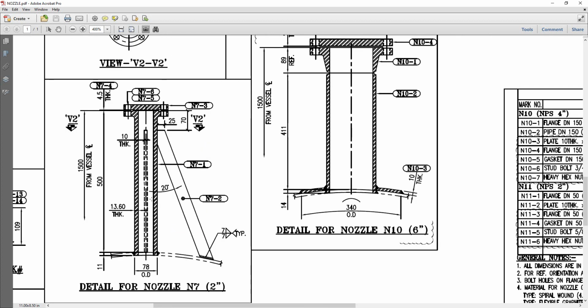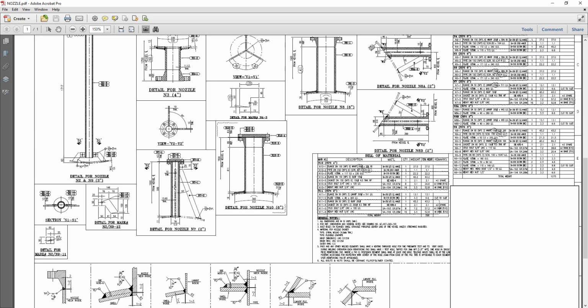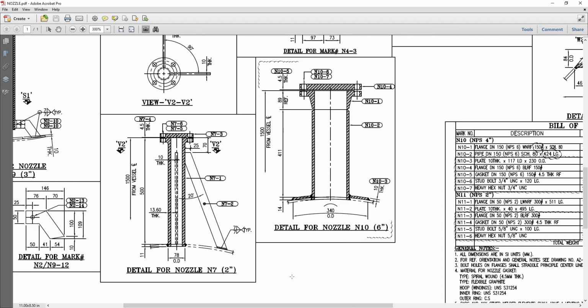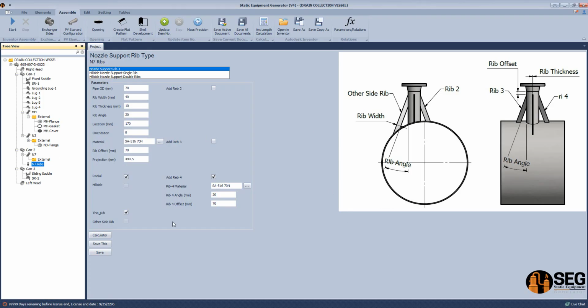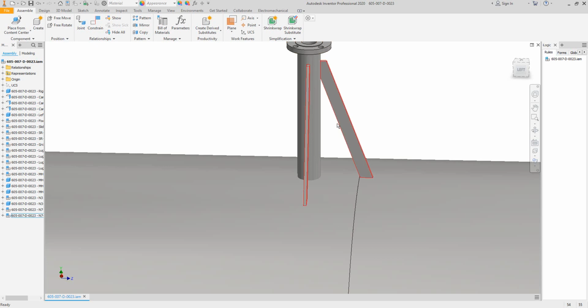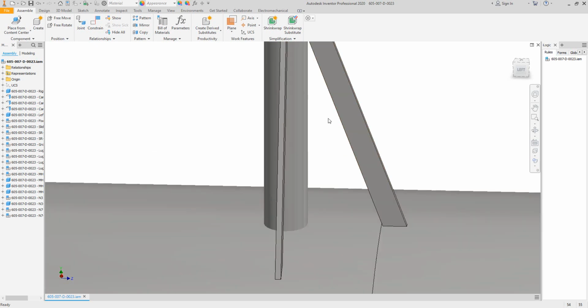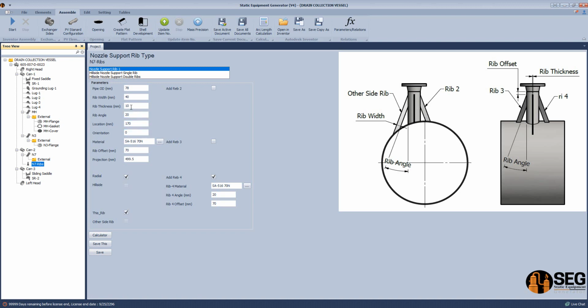Okay, on the longitudinal direction is not mentioned here on this view, and we already have one view only, so it's not mentioned on the second view. So we can change it. So we can increase this angle for that rib only, because you can control each angle for each rib. So here, we will increase the angle for the third rib, second rib, and click save.